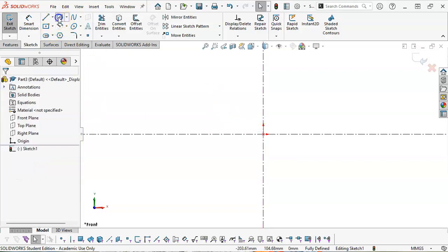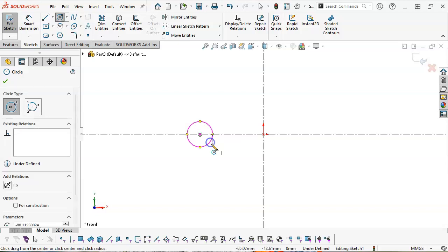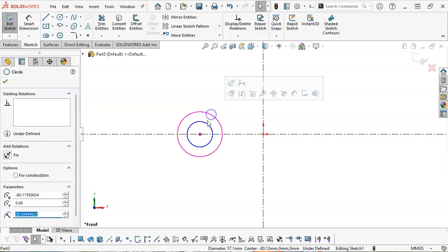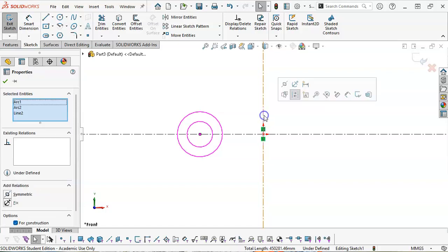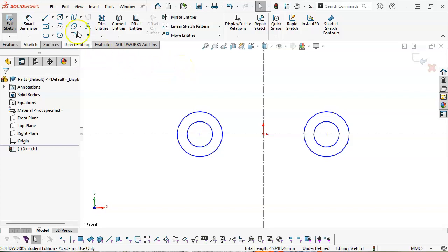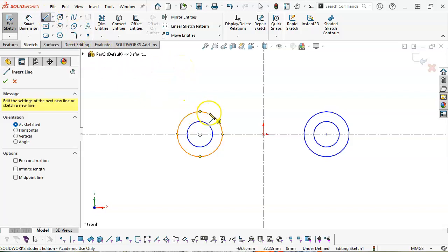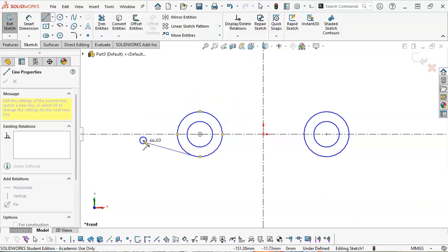All right, so if I draw my circle, we could do the arc, but I'm fine with contours and regions. So if I generate those two circles and select, control select, and we find our mirror entities, that's going to generate the two shapes. One of the things that you want to watch out for picking the circle: we go into the line command and I want to pick the circle, but it's going to go tangency, and that's really not what I want.